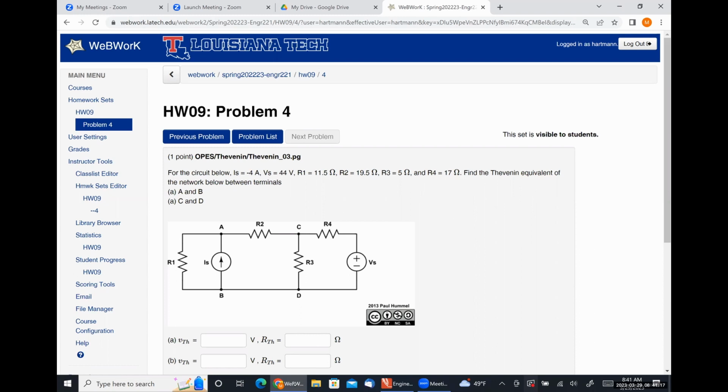Okay. When you find the Thevenin equivalent or the Norton equivalent with respect to a particular element, that element needs to be removed. If you're finding it with respect to an open circuited set of terminals, you don't need to remove anything. Just use those terminals. That's where your open circuited voltage is going to be measured. You're going to short circuit those terminals to find your Norton current. Okay. Yeah, no, it's a very good question. I'm trying to make sure everybody is on the same page.